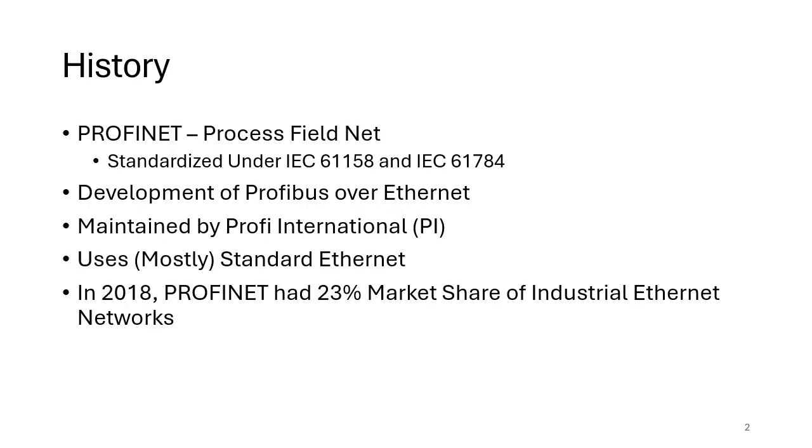So the history of PROFINET is that it's the development of Profibus over Ethernet. It's a very similar protocol to Profibus, but whereas Profibus uses a proprietary layer, although that was later standardized, PROFINET is standard Ethernet, although there are some caveats that I'll cover later.